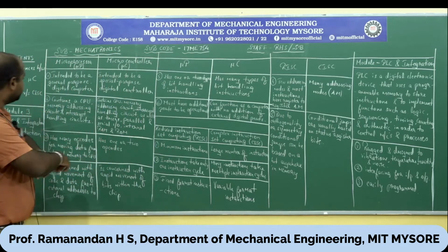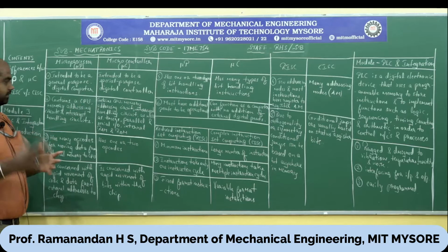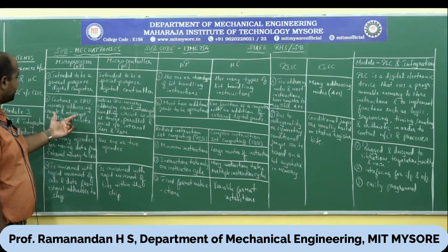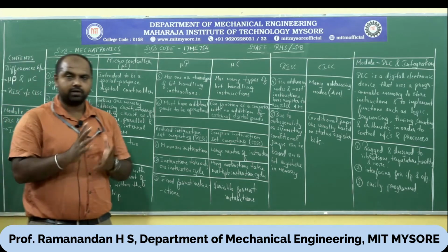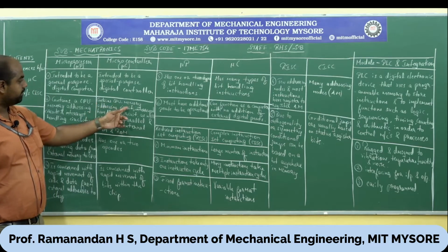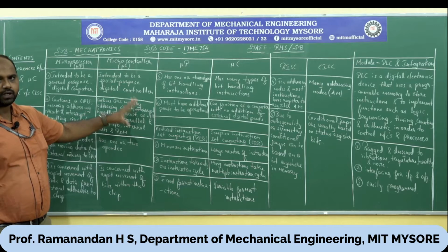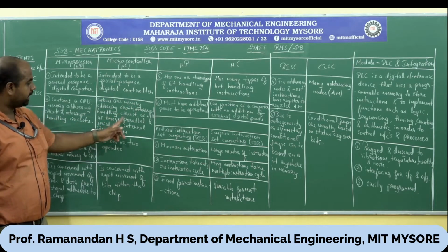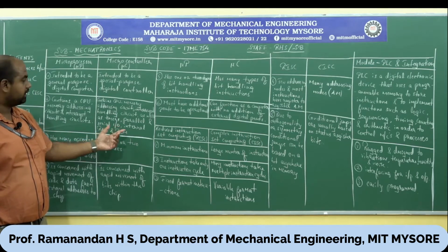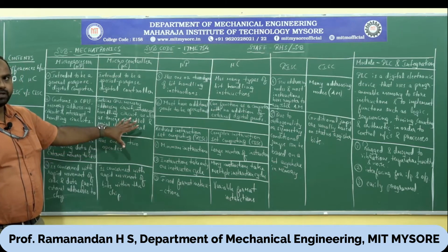The second difference is, what does a microprocessor contain? It has a CPU, memory, address and interrupt, which we already know. Coming to the microcontroller, it has a CPU and memory, all these regular things. That means it has a microprocessor, along with that it has a timer, parallel and serial input output controllers, along with internal RAM and ROM. These are the additional peripheral devices.